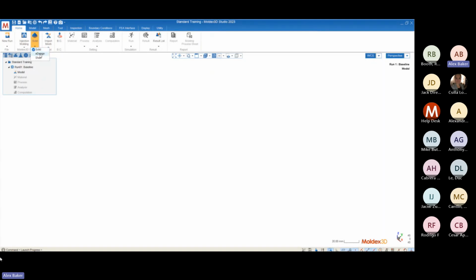eDesign is a little bit more automated. It's not a true 3D mesh. It creates voxel elements that are essentially 3D, but they don't follow the contours of our geometry exactly. Because of that, we have to create kind of an approximated mesh for our mold. So the eDesign strategy is nice for very complex geometries that are difficult to create the solid mesh for using our boundary layer meshing strategy. And that's pretty much the other option that you would utilize.